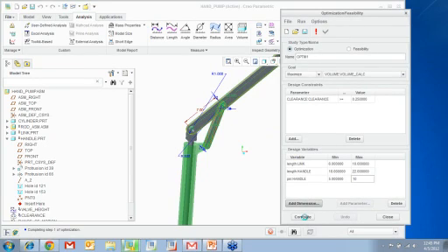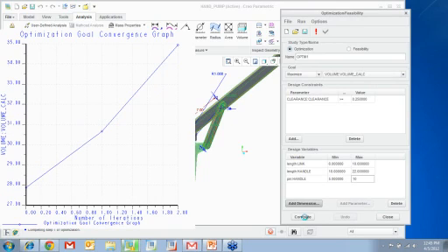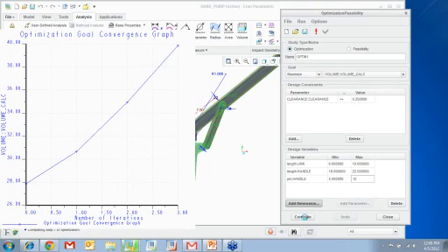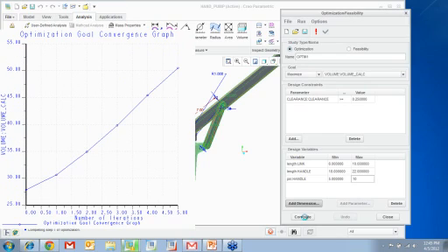So now it's going to try and change these design variables, maximize the volume, and also try to maintain the clearance value to be greater than or equal to 0.25. So here's an optimization graph. Now we need to make sure when we look at an optimization graph that it asymptotically reaches a straight line, and then we know that, hey, it converged well. It's still running the analysis as we talk.